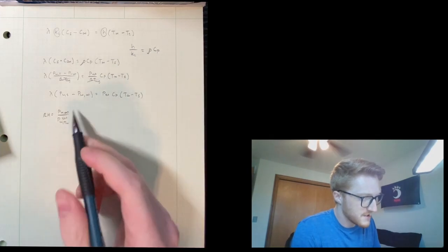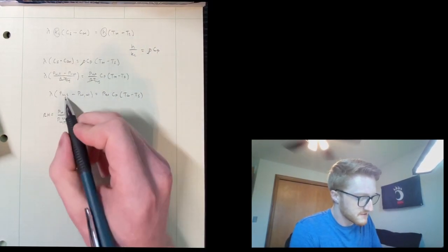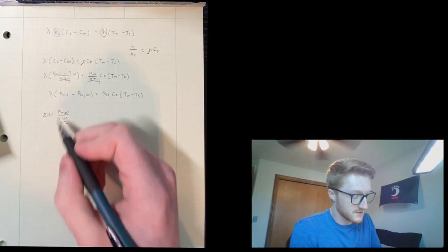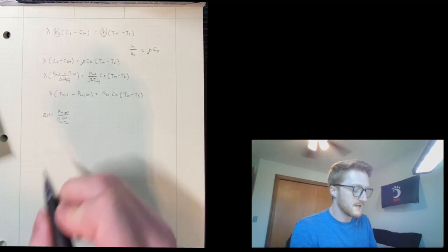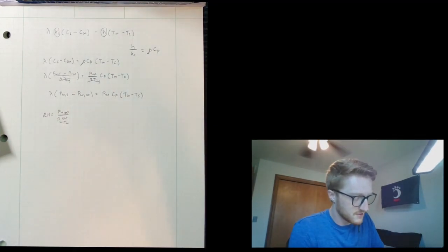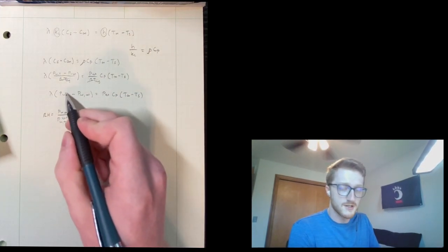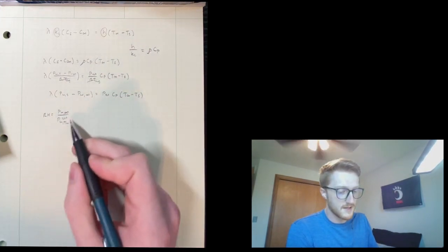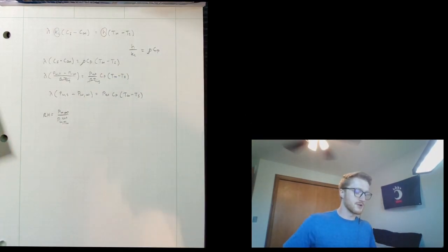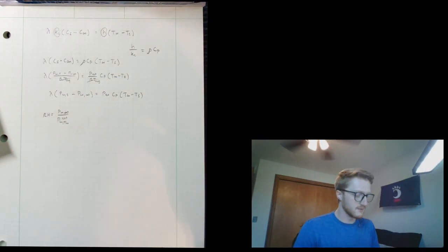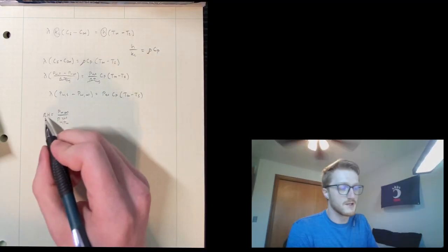We can find the partial pressure of the water in the air through this equation. But you may ask, how do we find the partial pressure of the water at the surface, which is equal to the saturation partial pressure of the water at the temperature of the water? You can use an Antoine equation to find this part of the equation and then plug it into here. Then you have your partial pressure of water in the air divided by the saturation partial pressure, and you can determine your relative humidity there.